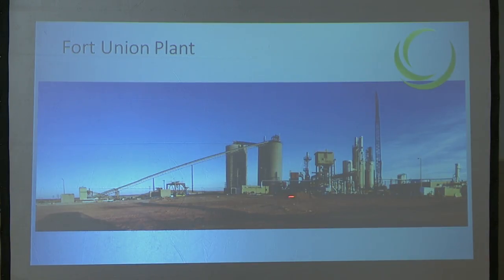From there, it's pneumatically conveyed to this silo, which is our granular coal silo. And from there, it's again pneumatically conveyed through our reactor, which is right here. It's 40 foot tall by 5 feet wide, a real small footprint. It goes through our heat exchanger to cool the carbon down. Once the coal is impacted with the heat, the process gas is driven off, and we have concurrent flow as opposed to countercurrent flow like the other system.